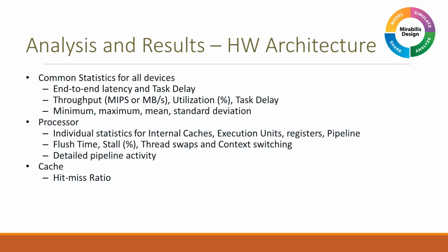Now, analysis can be of many types. If I look solely at the processor, I might look at the pipeline activity, or the pipeline utilization. But what I might also try to see is how much thrashing is happening, which means how many times the prefetching keeps on going to the memory. And these will create a large percentage of stalls. So other ways, maybe move from a burst to a streaming-based architecture to see whether the performance improves. Things that you can try and analyze.